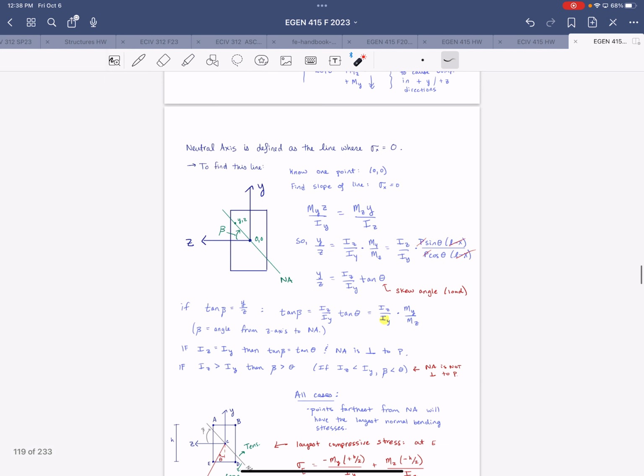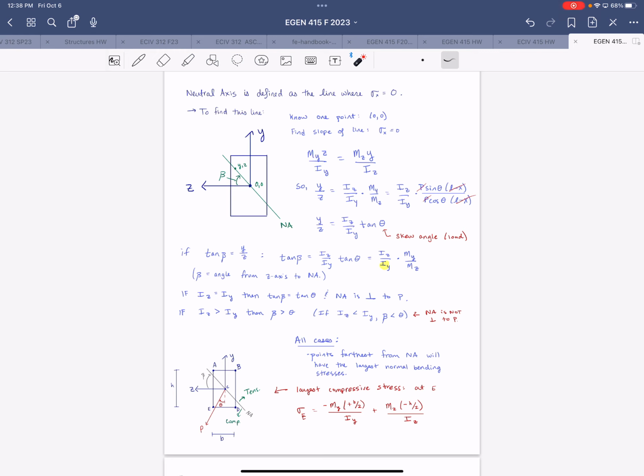I've got one more question on this one. In steel, we had a W section roof purlin on a 30-degree slope with a gravity load straight down. Our strategy to calculate the capacity, or size the purlin, was to break that load into x and y components, perpendicular to the strong and weak axes. Is that equivalent to what we're doing here? Yeah, it sounds like it, based on what you just described.